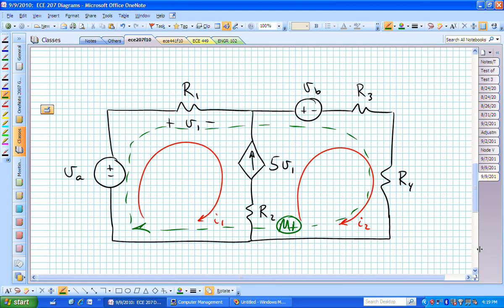Look at 5. Five has to actually have the units of current over voltage. It's a scaling factor. It's hidden to you, but V1 is a voltage. That's a valid question. Very good question, actually. But 5 has to have the units of a conversion factor of amps over volts, so that when it's multiplied by V1, you get amps.